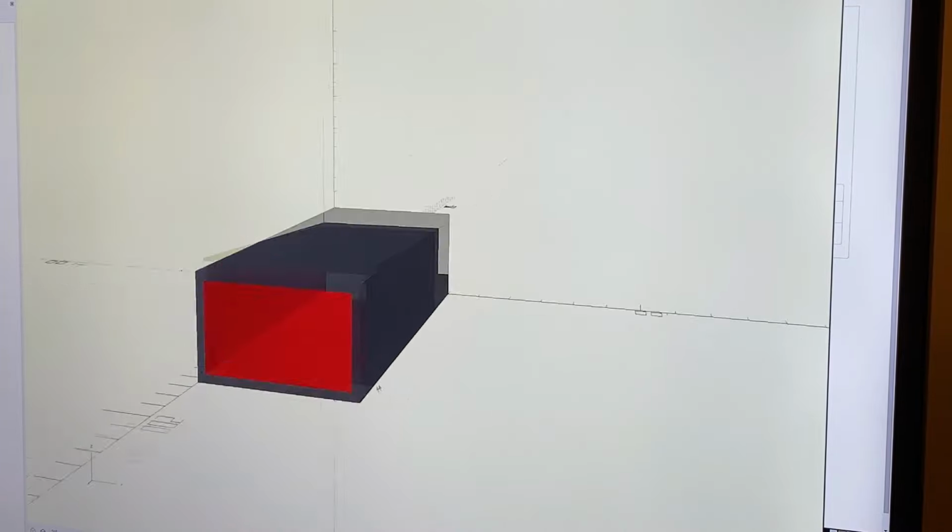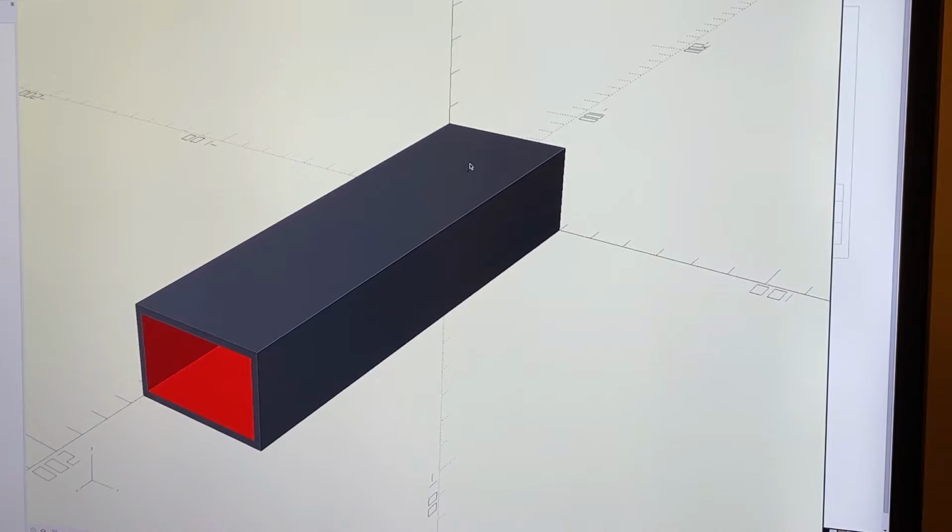The next step is we're going to have to remove the holes that the bottles will sit in. And later on, I'll show you how we can configure multiple holes. It doesn't have to be just 1 or 2 or 4. It could be however many you want. But I want you to see how we create those holes by subtracting a cylinder from within the rectangular prism. So here's kind of what that looks like.